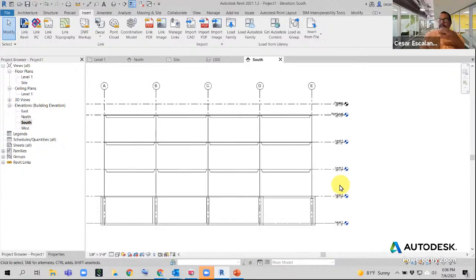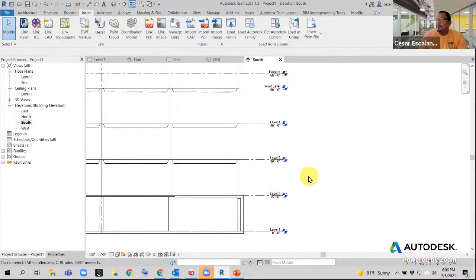So copy monitoring establishes a relationship. It recreates level geometry, places it at the same elevation, the same level extent, and the same level name, and then establishes a relationship between these 2 pieces of geometry. If one of them moves, then that's going to trigger a coordination review warning. And a coordination review is a Revit attempt to alleviate inconsistencies between copy monitor elements. So let's recreate the levels using copy monitoring.